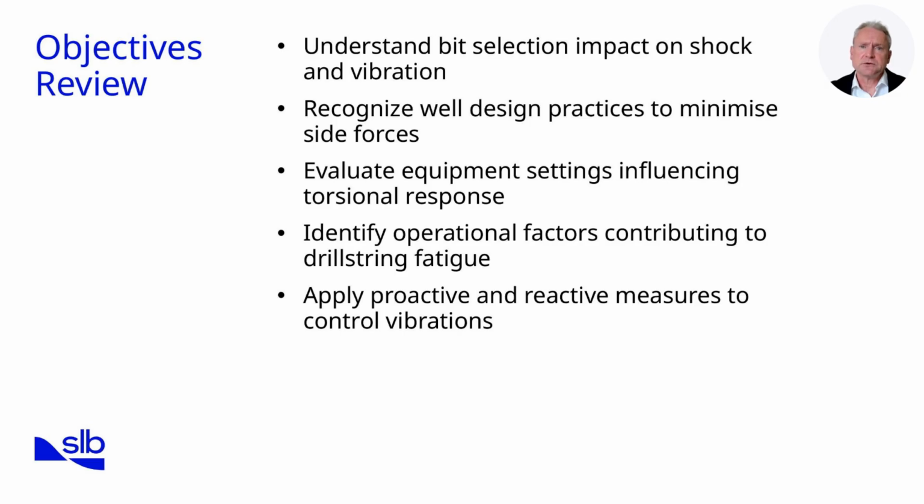Let's take a moment to review the learning objectives we set at the beginning of this sub-module. First, we set out to understand the impact of bit selection on shocks and vibrations. We explored both PDC and roller cone bits, highlighting how each design influences stick slip, whirl, and axial loading. Second, we examined well-designed practices that minimize side forces. We discussed tortuosity, friction, and mud system choices, and how each factor affects vibration.